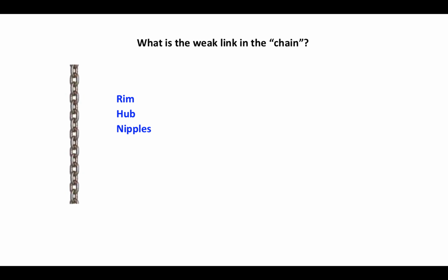With respect to spokes, we already talked about the problem of spoke tension possibly going beyond the yield point of the spokes. There's also the possibility of repeated metal fatigue causing breakage at the spoke elbow. Unquestionably, with the rims, there's concern about cracks and the possibility even of nipples pulling right through the rim.